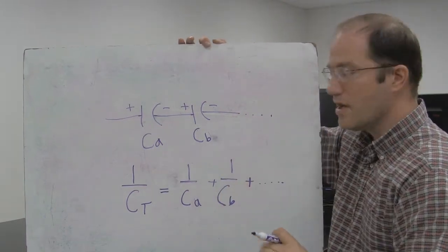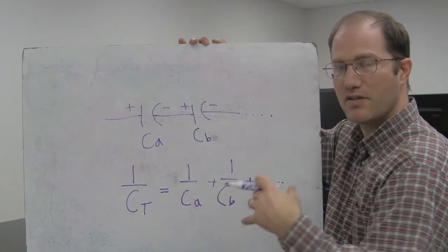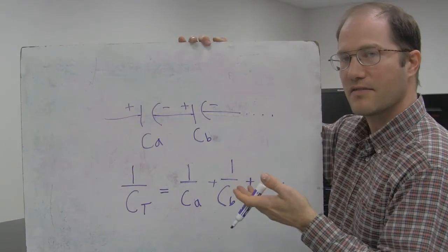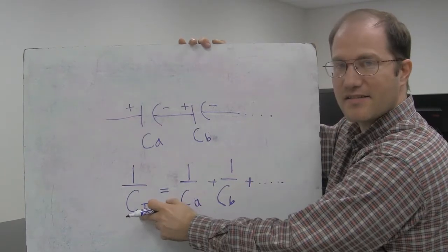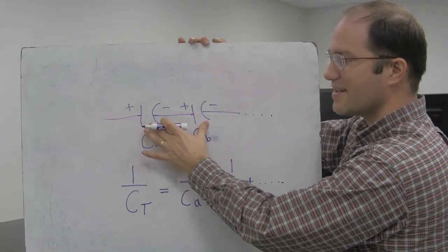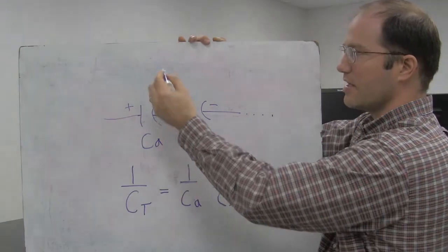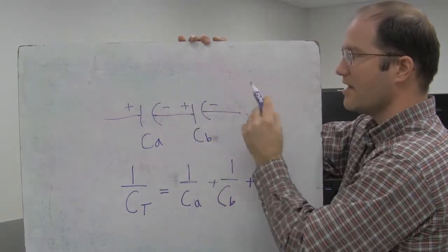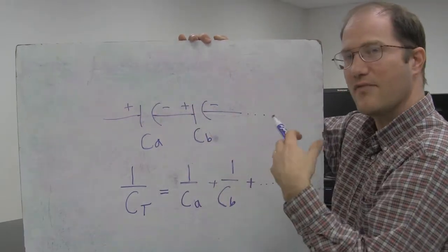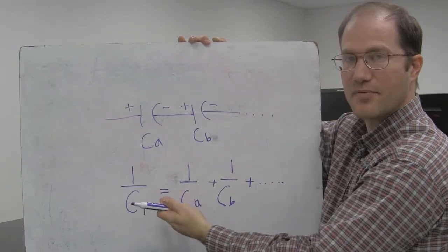That formula holds true. So you should be able to predict, based on what CA and CB are from when you determine those values from the curve fit, what our total capacitance is when you place them in series. And you'll actually put the two capacitors in series electronically and do the experiment again. You do the discharge experiment again, curve fit it, and you'll get a value for your total capacitance. And then say, was it close to my predicted value?